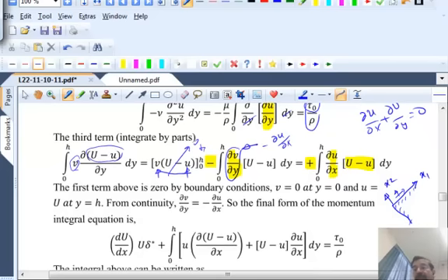If you have a bluff object like this, a curved object, and the flow is coming like this, and you have a boundary layer that is developing like that, then you need to set up a local coordinate along the curve. This is where ideas from curvilinear coordinates will come in handy. So you'll set up a coordinate that is going along the contour of the shape of the object, and one that is perpendicular to that. And so you will still have a perpendicular velocity as being 0 in all these generalizations.